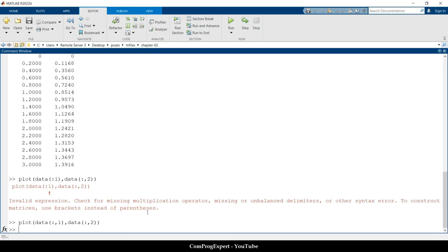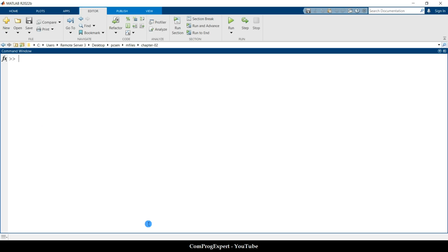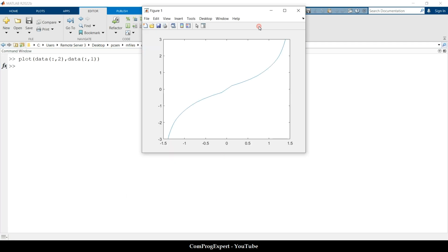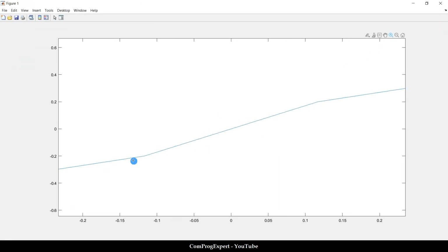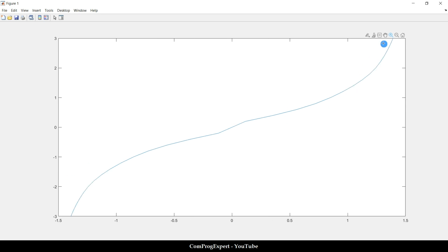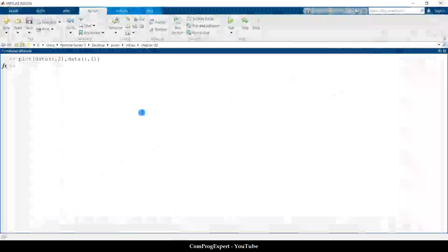In MATLAB, if I plot this 1, 2, you can see this graph. Okay, actually, we should smooth this graph and import it into Simplorer. If we don't smooth this graph, we have some numerical issues, not important again for this analysis. So consider this important point.